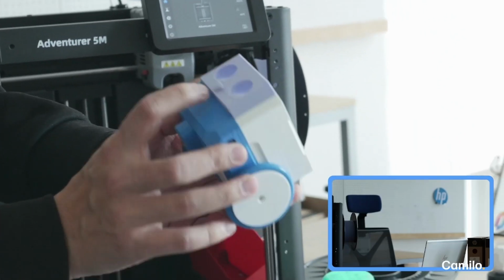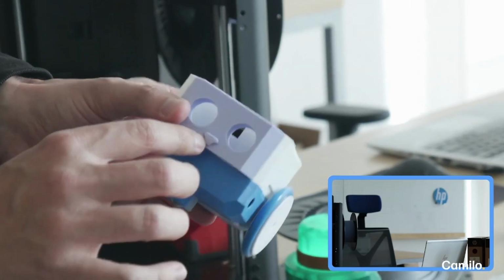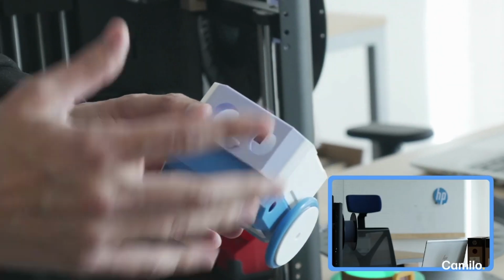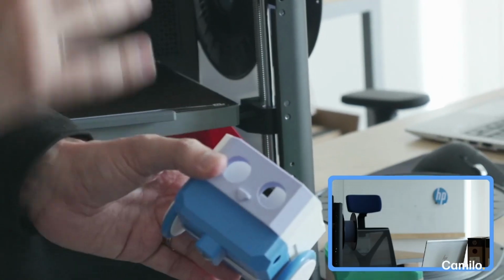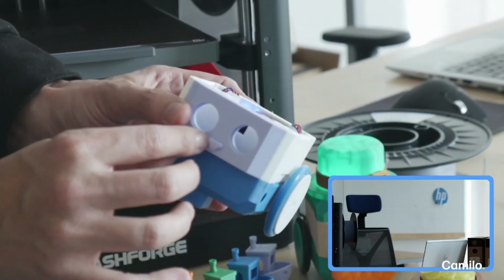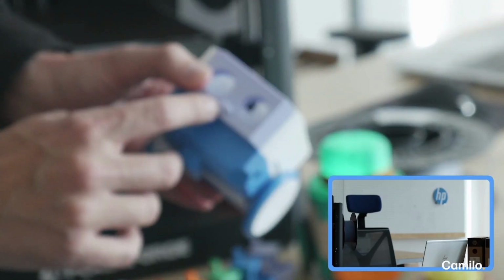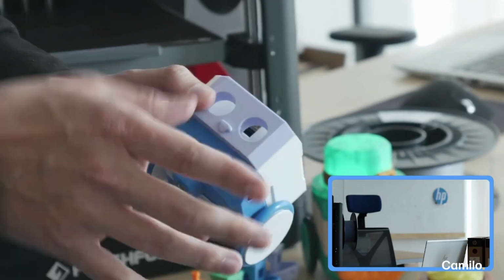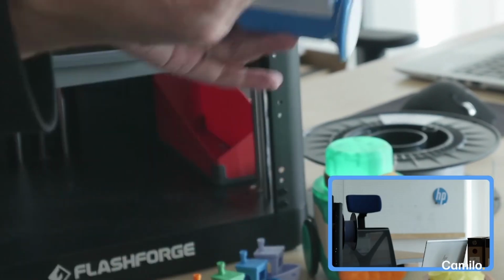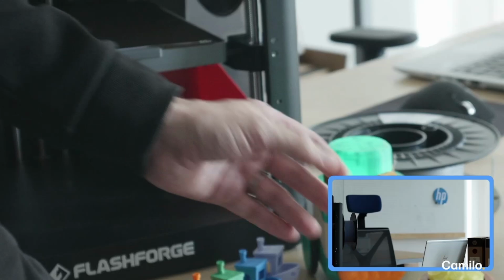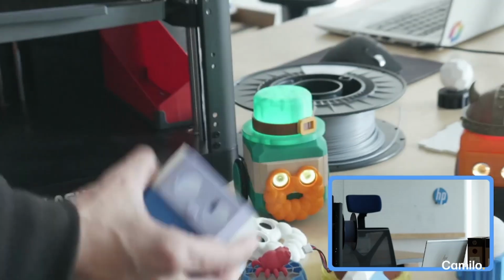Looks very cool. Now, many might ask, what if I want the nose in a different color? There are printers that have multicolor, but my favorite approach on a single extruder printer is to just change the filament in the middle of the printing. We could have changed it to black, for example. It takes a little bit more time, of course, because you have to change it, but then it will be black, or you can paint it. There are many ways you can go around with 3D printing, many options, and that's what makes it so nice. Very cool.